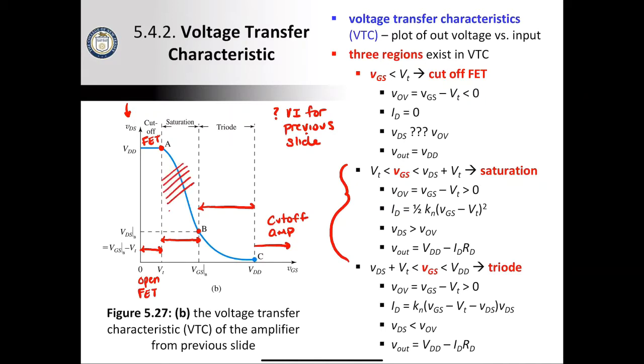And then second, which we haven't talked too much about, is linearization. So we want an input-output relationship for our amplifier that's linear. You buy an LM741 off the shelf, and you get a constant gain of 5 or 10 or 15. So if we were looking at this as V in versus V out, it would be a straight line. We don't have exactly a straight line here, and as you get closer and closer to the edges, it becomes even less straight or more nonlinear, which is going to be a problem, but we're going to address it.